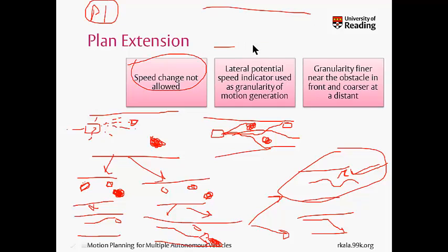And the second thing is that whenever I work with such kind of methods where inside my head I'm moving the vehicle on some trajectory, granularity is a principle that comes in. So suppose in the same scenario, I can see that the vehicle and the obstacle are far ahead, so I can move them with the same speed. I can make them jump by some large amounts. Now the vehicle is near, so I'll have to make the vehicle jump or change its steering by smaller amounts. So that's what I would be doing. Here, large amount, far off, again far off; obstacle near, then small amount. Suppose I'm turning right, then smaller amount and smaller amount. So even though the speed is the same, my jumping speed, or my granularity, is changing.